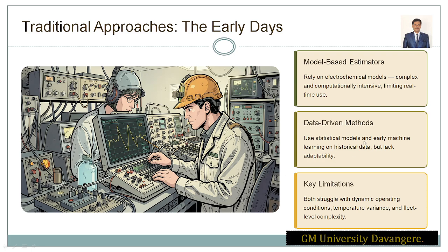Check the various patterns of the cells and what is happening inside. Then you can see the conditions under which it is going to work, and check how many cycles have been collected. If you see the collection of a thousand cycles of data, then you fit the curve for SOH. You can take a sample of A into cycle plus B into temperature plus E, then you can see the actual SOH values. So that is what the statistical data will tell us.